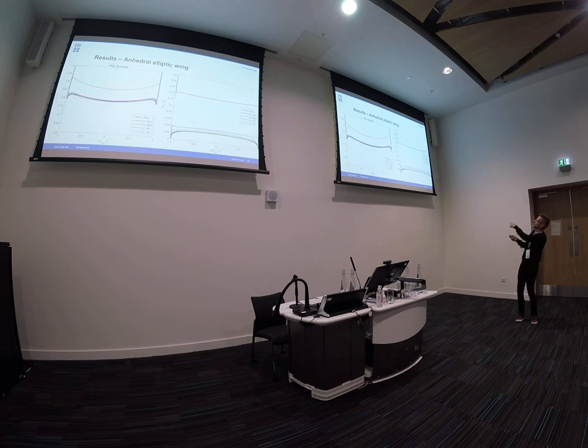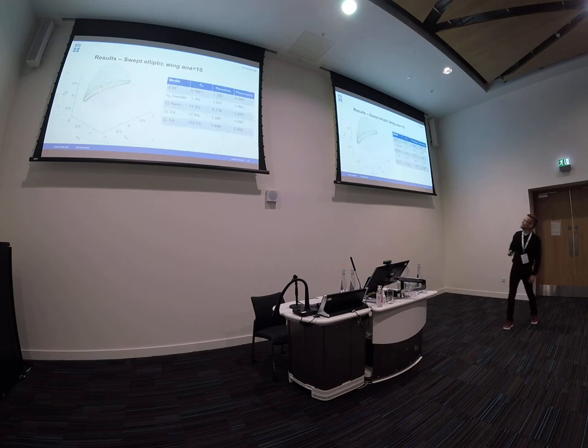Again? Yeah. Now you sweep it. That's a little bit numerically more tricky. This is where you have these new forces coming into the game. It does look kind of good, I would say. Now these and these disagree a little bit. I speculated a bit about why that is. Maybe that's because the wake is not force-free when you do the far-field approach. You also include the forces on the wake, actually.